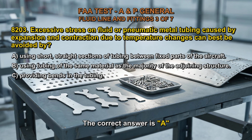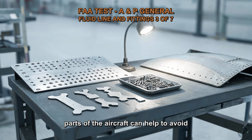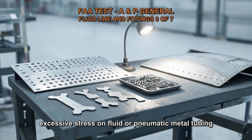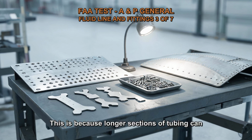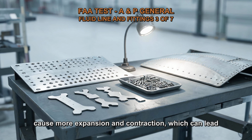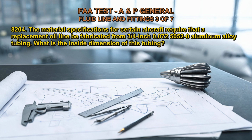The correct answer is A. Using short, straight sections of tubing between fixed parts of the aircraft can help to avoid excessive stress on fluid or pneumatic metal tubing caused by expansion and contraction due to temperature changes. This is because longer sections of tubing can cause more expansion and contraction, which can lead to stress and potential damage.